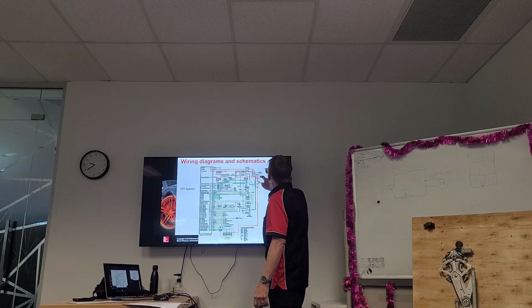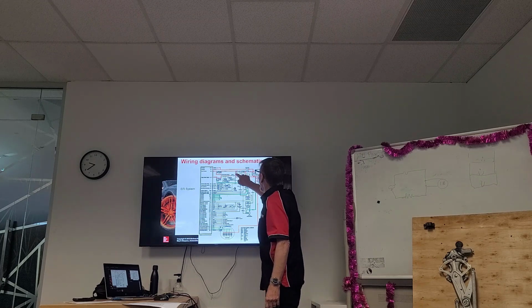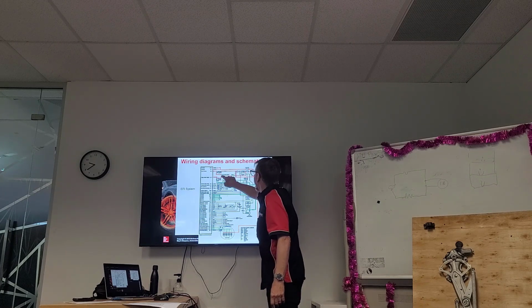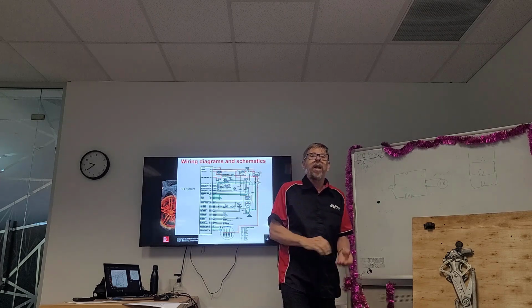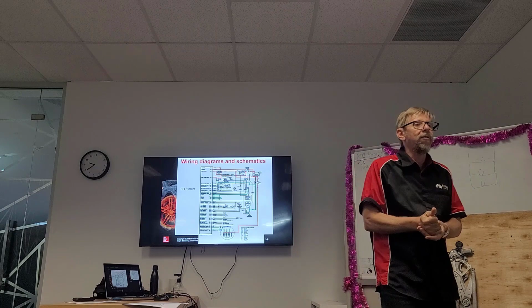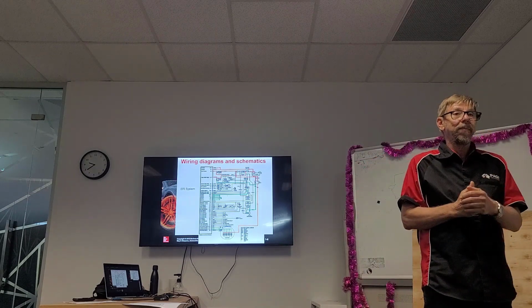And I find out that if I don't have power going to that solenoid, obviously I don't have power going to this relay, and I see there's a fuse there. Where am I going to look? Fuse, check the fuse. Fuse number 11. Wiring diagram, map it out. Does that make sense? Okay.